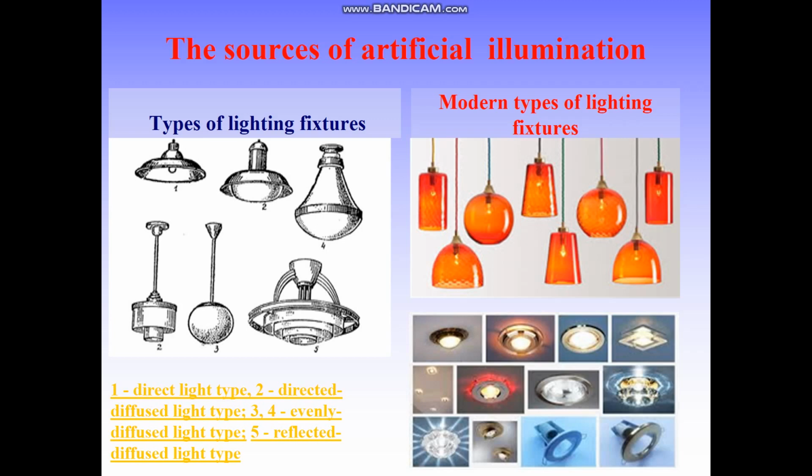There are lamps of direct, scattered, and reflected lighting. The lamps of direct light are usually filament lamps. Almost all light flux of these lamps is directed downwards, gives sharp shadow, and does not provide uniform distribution of the light. The bright glare of this lamp has a blinding effect. The bright source of light causes fatigue of eyes, adversely influences the nervous system, and therefore the work capacity is reduced.